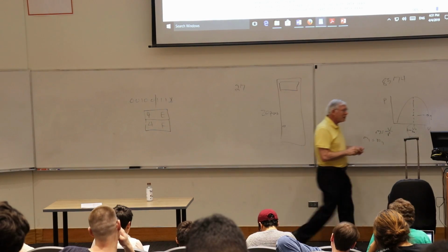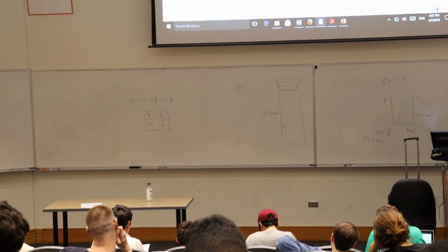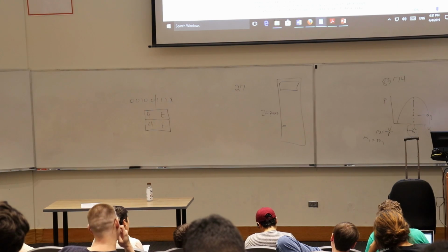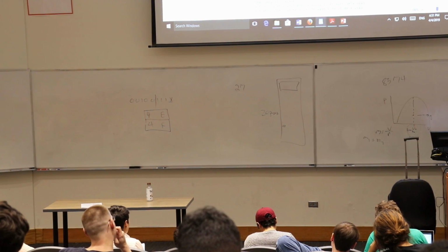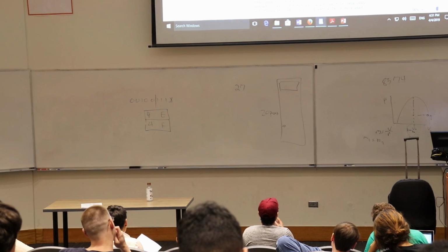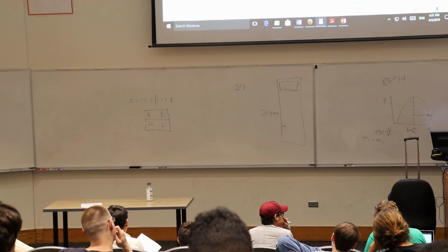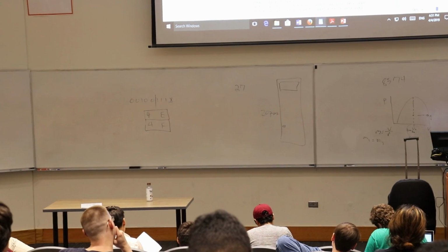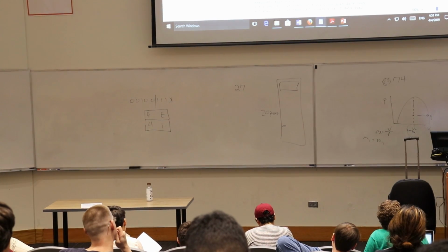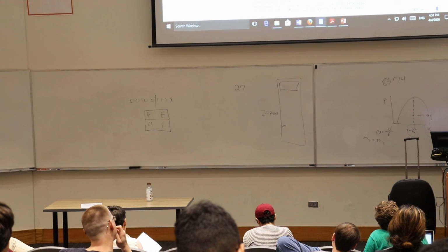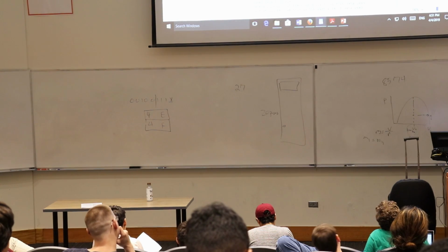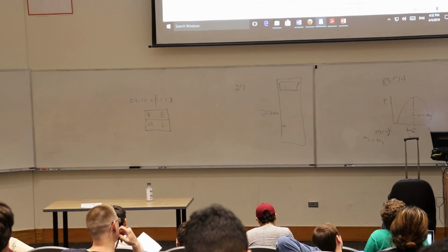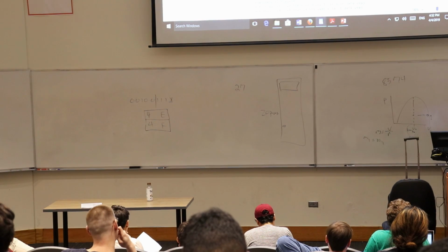No, they don't do that. They make you read through the whole dang thing until you get to that part, and then even there they kind of obscure it, and they probably put it in a table of several other parts, and then you're not even sure which table entry refers to your part. And then you have to go dig your chip up and look at the additional numbers on it. In this case, 8574A has a different set of addresses. So you have to pay attention to which it is.